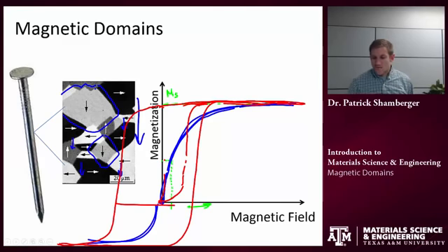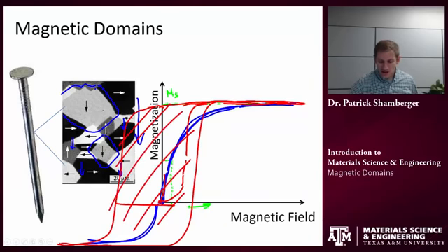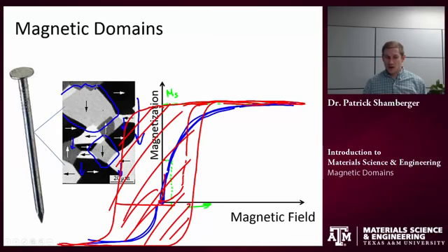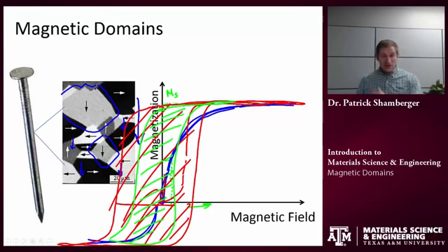And so this is describing how much magnetic field it takes to switch the magnetization one direction versus another direction. So those hard permanent magnets in the generators, I need to have a large hysteresis loop, because the larger this area, the more energy it takes to reverse the direction. And if I'm thinking about a generator, I don't want the direction of those permanent magnets to reverse at all. The hard disk is going to be somewhere in between. I need to have it relatively hard to switch because I don't want those magnetic bits to switch spontaneously, but I can't have it too hard or else it would be too difficult for me to rewrite what's on that magnetic disk.